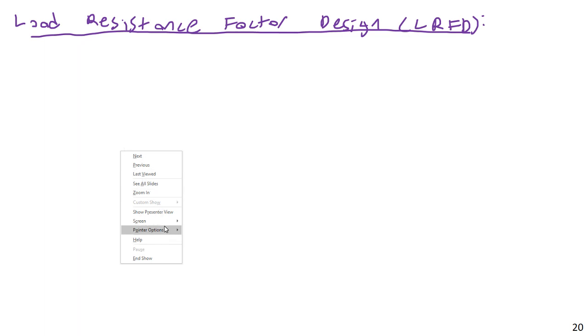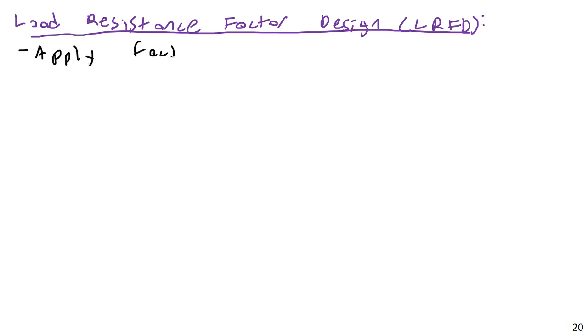Well, I mentioned this was the more scientific approach, and what I mean by that is these factors are usually chosen from a great deal of historical studies and laboratory studies. So, again, we're going to apply factors to both loads and resistance independently. Again, loads are your actual demand, and your resistance is the strength of the structure.